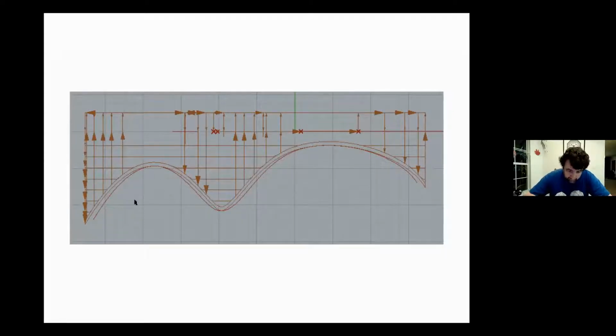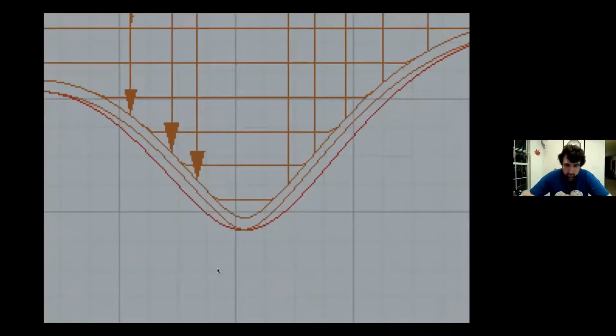So let's zoom in. I apologize for the pixelization of these images. I need to make some which are of a higher quality, but you still will get the basic idea. So these horizontal lines, those are the rough cuts where you're just removing material. And they finish off in this curve here. And that sort of finishes the roughing. That's the process you do to remove the material that's just in the way, that you just need to get rid of. And then you want to do the finishing to get a good quality.